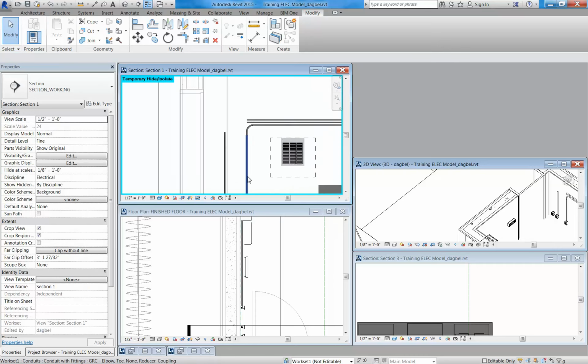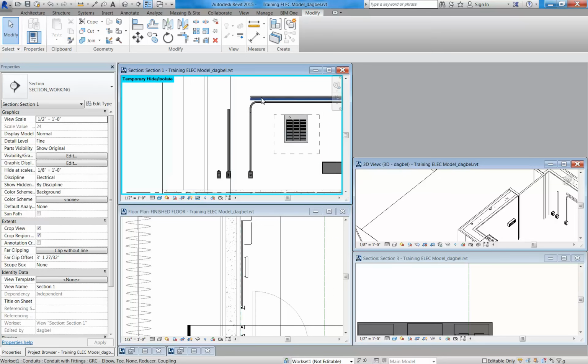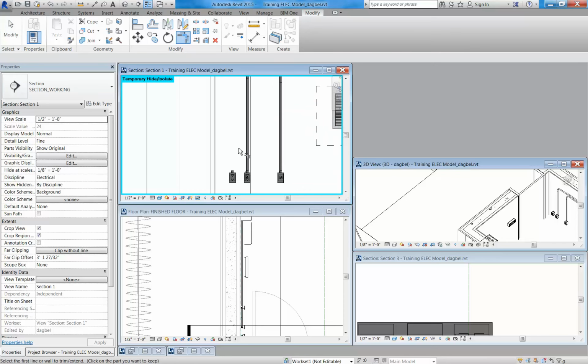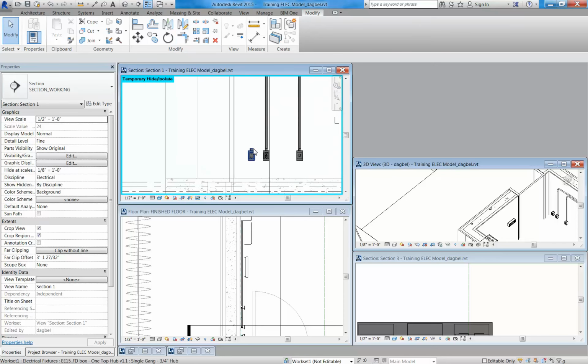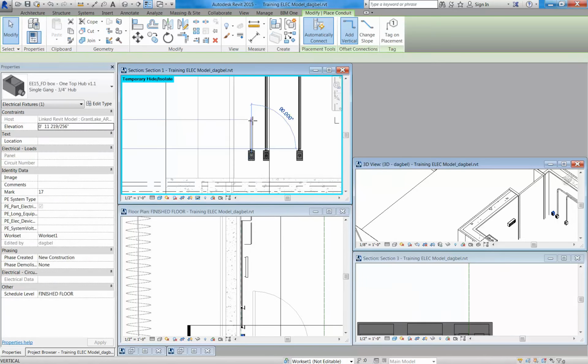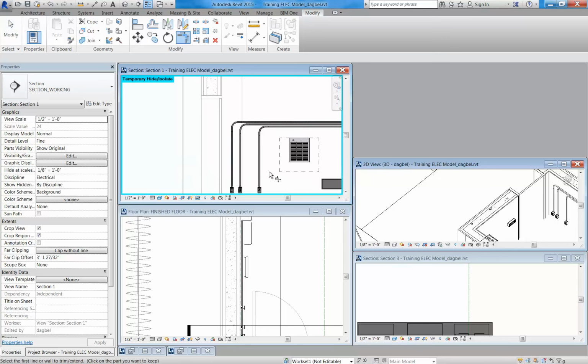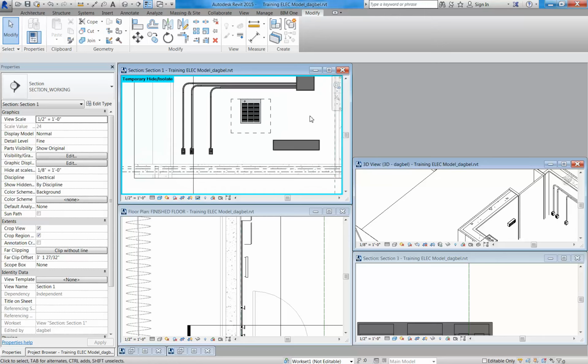If you want to connect 2 existing conduits at the corner, you can use the trim extend to corner, select the 2 conduits, and it will create whatever bend you have specified. Let's do one more. You can also push TR to get that same effect, but you do have to have a conduit at the other end, so we'll start drawing a conduit here. So now we've created 3 conduits.